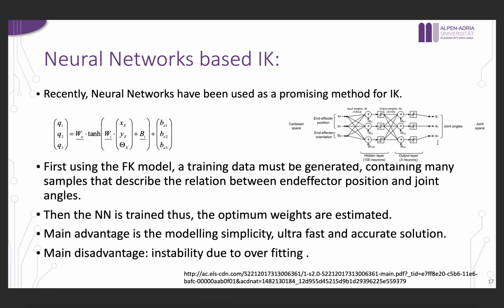Then I do this movement over the three combinations, so I am changing the position of the robot arm using the three ranges. When I'm doing that, I can always calculate the position of the end effector using the forward kinematics, and then I can store this data. Now I can do the inverse by training a neural network to take the positions as input and the joint angles as output.